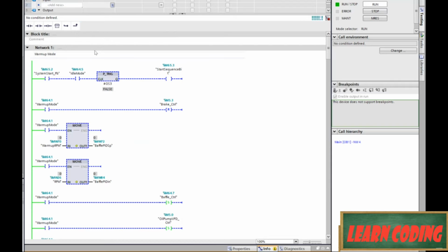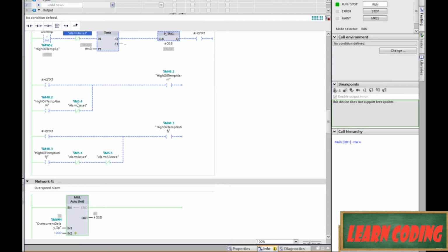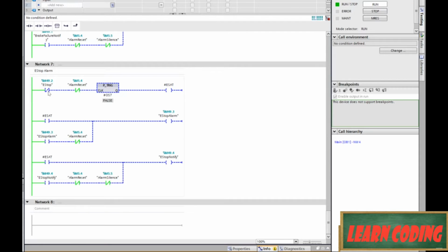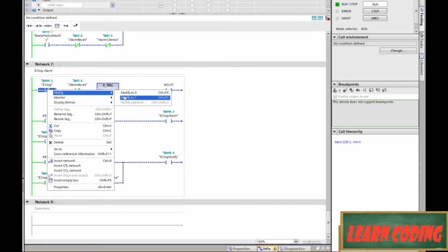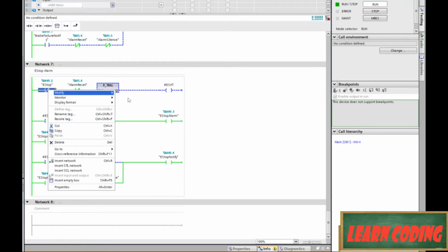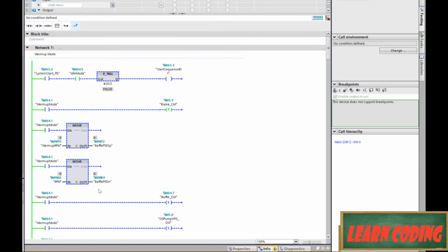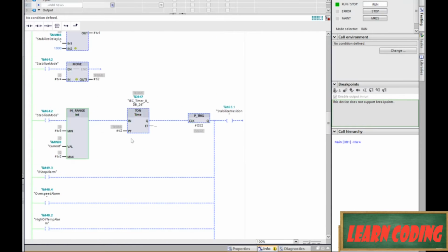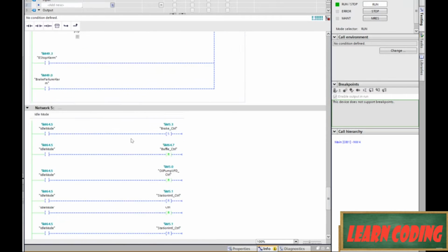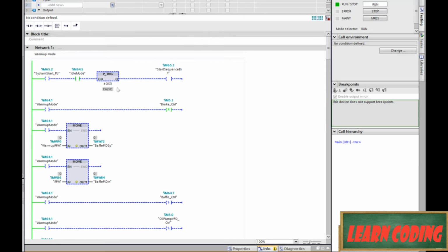So I'm going to do this another way. I'm going to just go and e-stop us. So we're in alarms over here. And let's just modify e-stop to 0. Modify it back to 1. And then toggle our alarm reset to 1 and then back to 0. Okay, so now I bet we're in idle mode, and if we are, yay, that's one thing that works. Okay, good, we are. Nice.